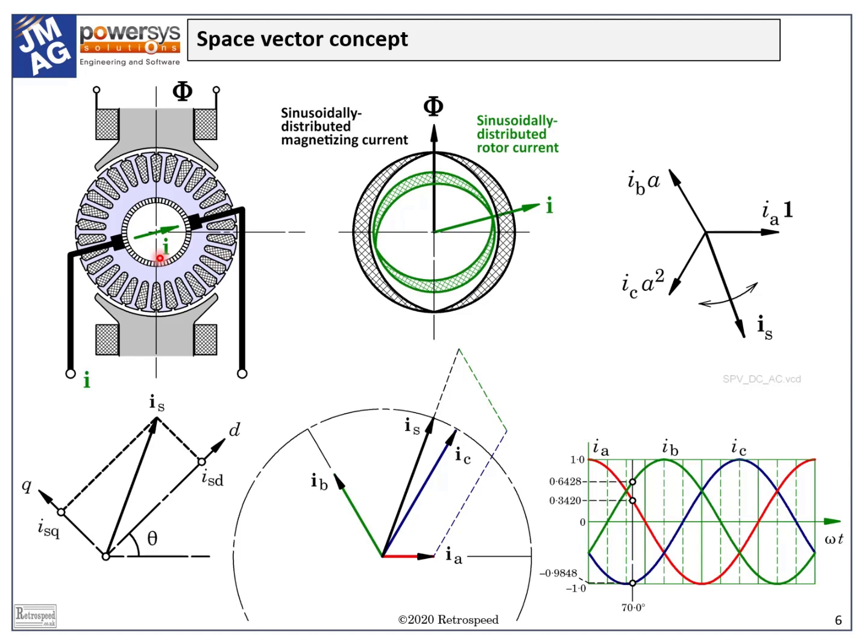The pattern of ampere conductors which establishes the armature reaction flux has a fixed shape or spatial distribution. But once that distribution is given, we can focus on just two parameters that define its main effects: the magnitude I in amperes and the direction, which is determined by the angular position of the brushes.